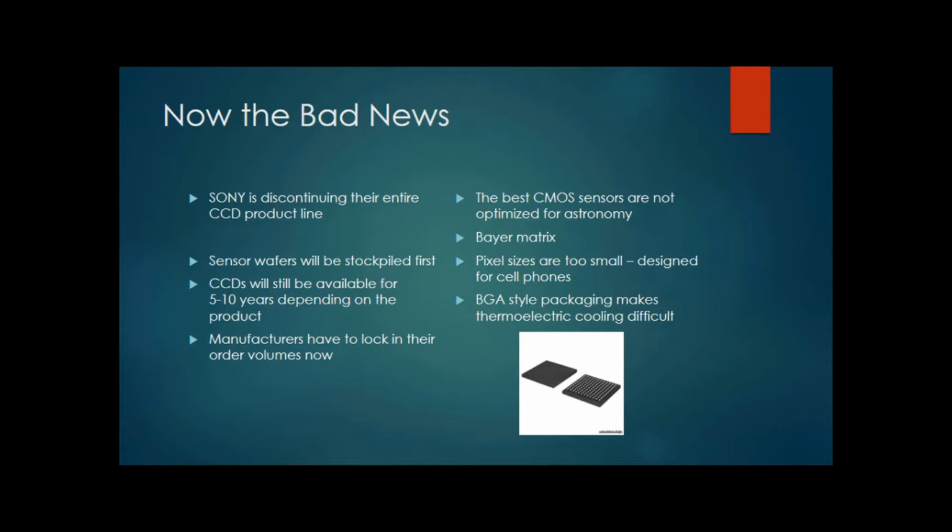So they're making it harder to make a cryogenic camera like we use for our CCDs, where we chill it down to minus 20 or 30 degrees for a low dark current. They're making that difficult. So hopefully they'll make new sensors that don't have this design that will actually be able to properly chill.